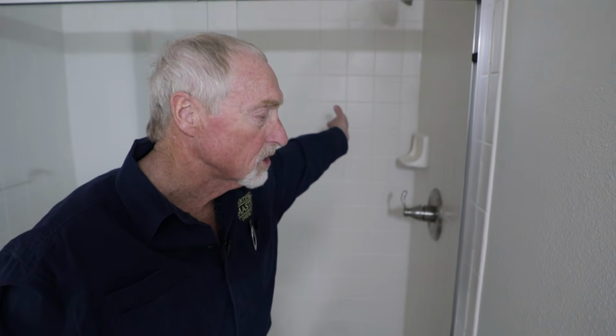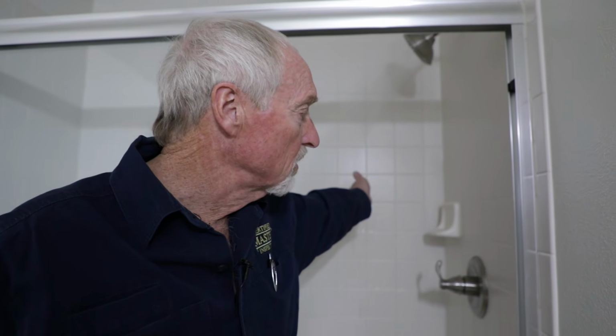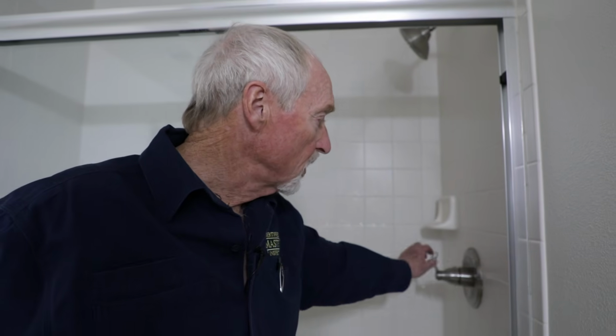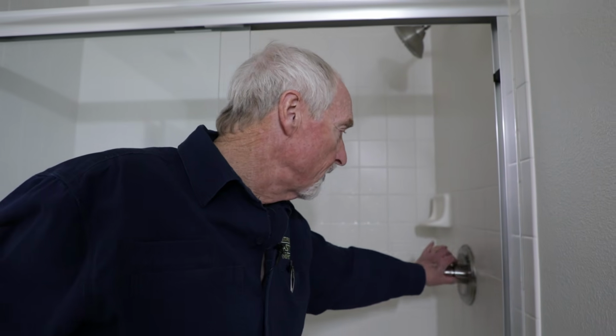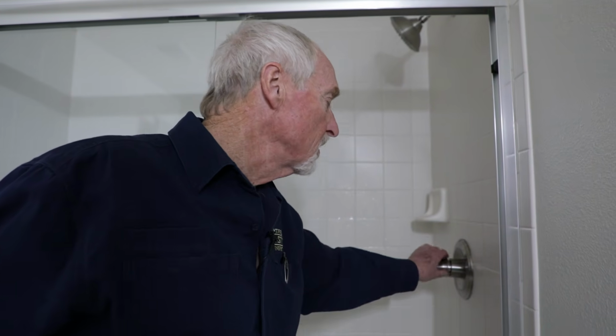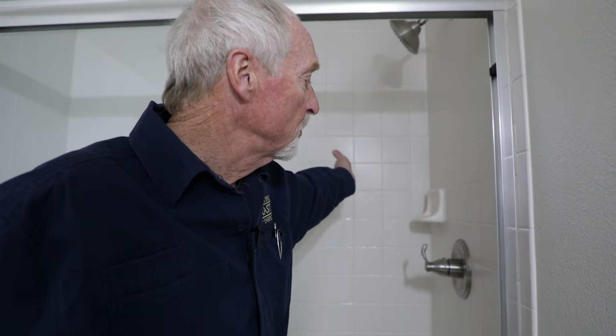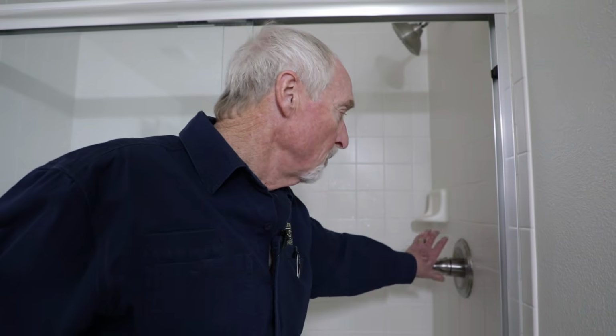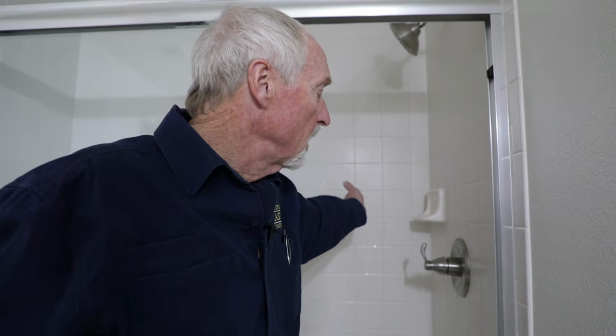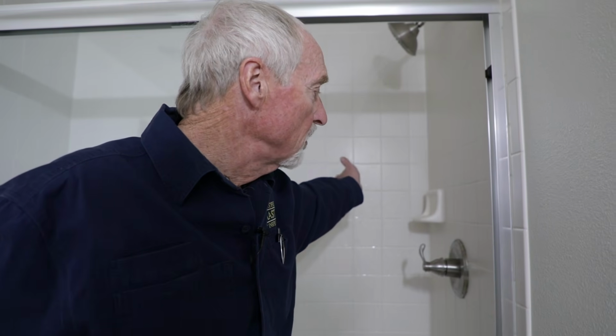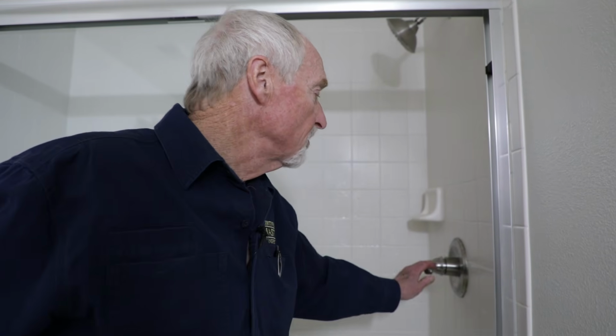If I'm suspicious that it's above that, I will go grab a thermometer and double check it to see what the temperature is. These new fixtures have an adjustment in them so that the water will mix inside the fixture and you can adjust it so that you don't have it running too hot. That's important for mainly kids. So this one's doing good.